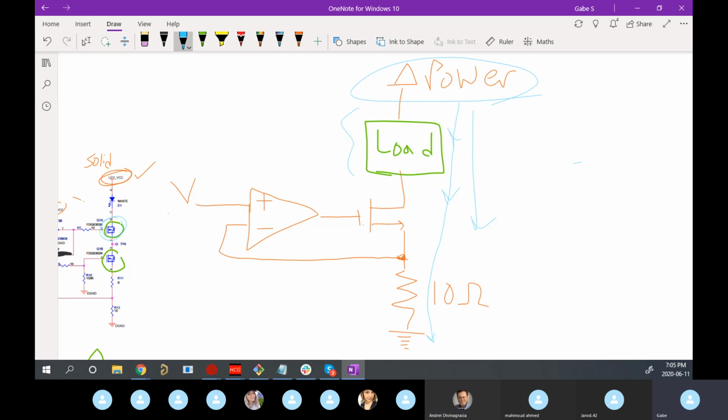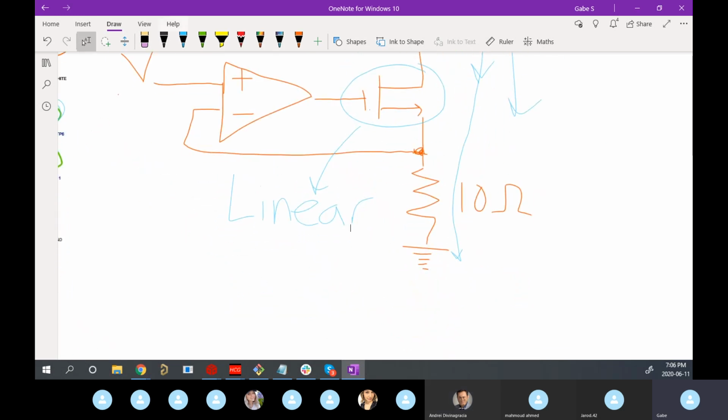And so what actually happens here is that you're controlling this transistor in its linear range. You're not actually using it in saturation, so it's not being used as an on-off switch like you normally use them. Oftentimes we use MOSFETs as on-off, and that's cool. Probably 90% of the applications are like that. That's what you use in saturation mode, when your gate voltage is above the threshold. But in our case, we're using it in linear mode.